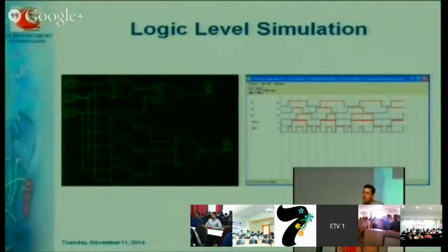So here you can just view, and these types of simulators give you a fast idea about the functionality of your program. From here you can easily check whether your circuit is working as per your requirement or not. All of us are well aware of the working of this full adder. So once your full adder is designed with the help of these logic gates, you can easily verify your truth table from these waveforms.